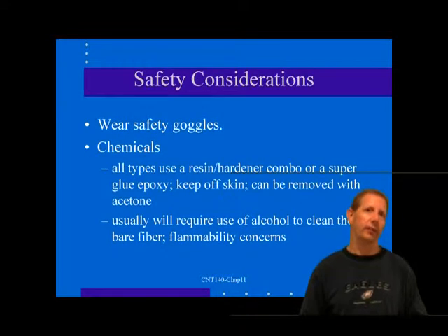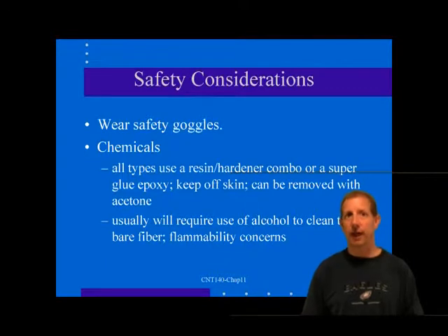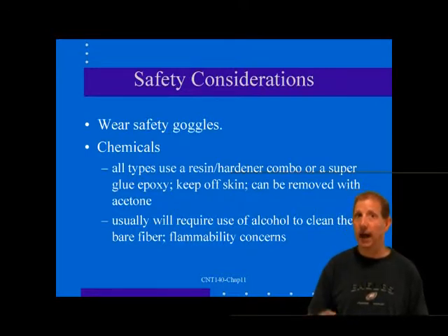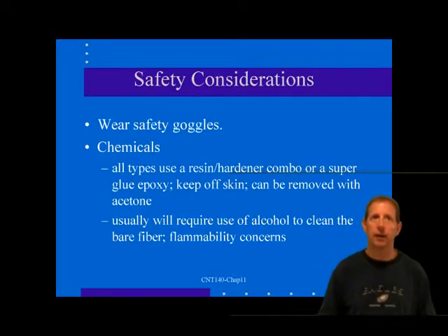Safety considerations. Fiber optic technology has safety aspects that are quite different from those of copper cabling. As long as the proper procedures are followed, fiber optic installation should be as safe as any type of cabling. Eye protection in the form of safety glasses should be used for all fiber assembly work.